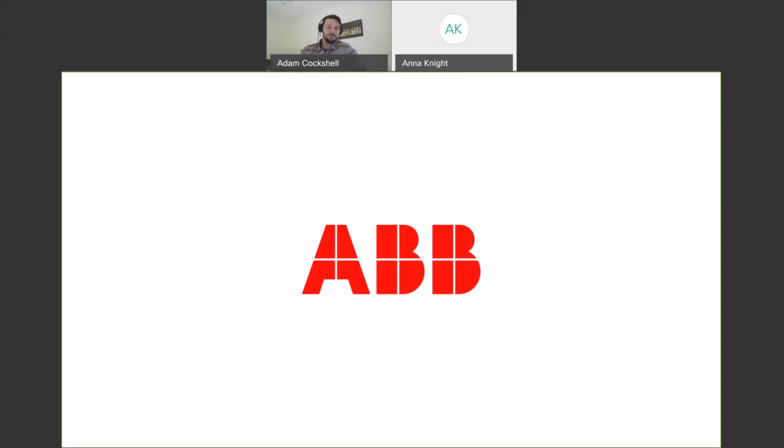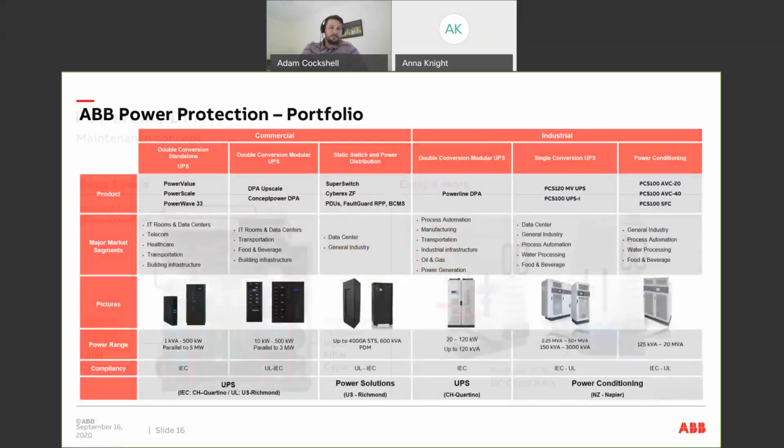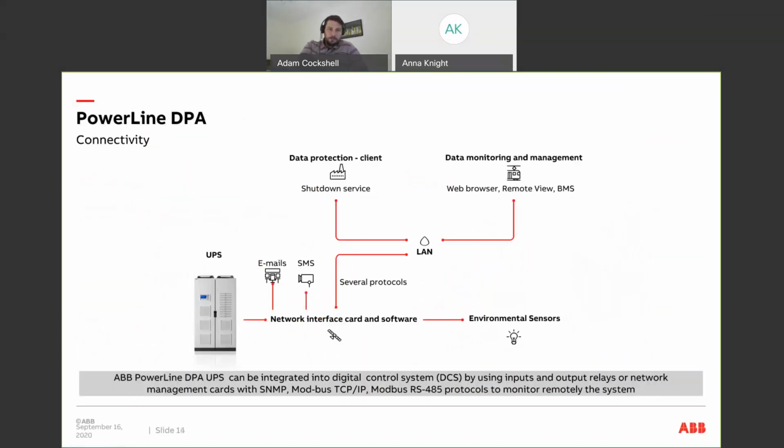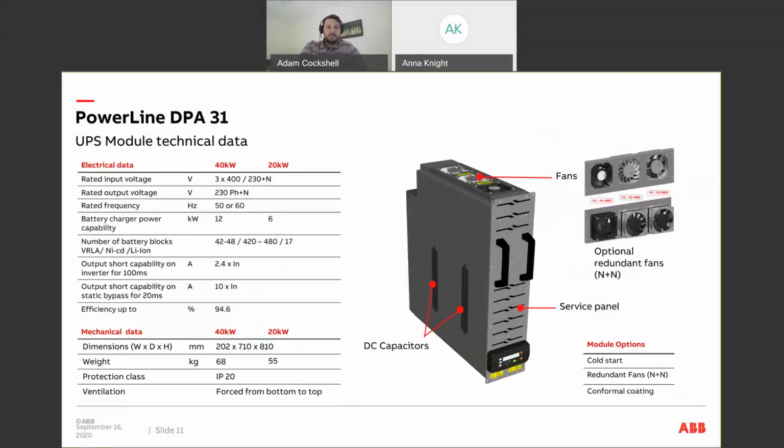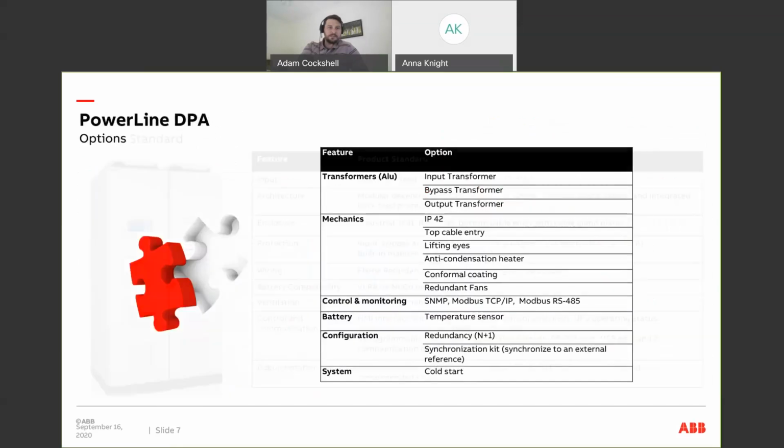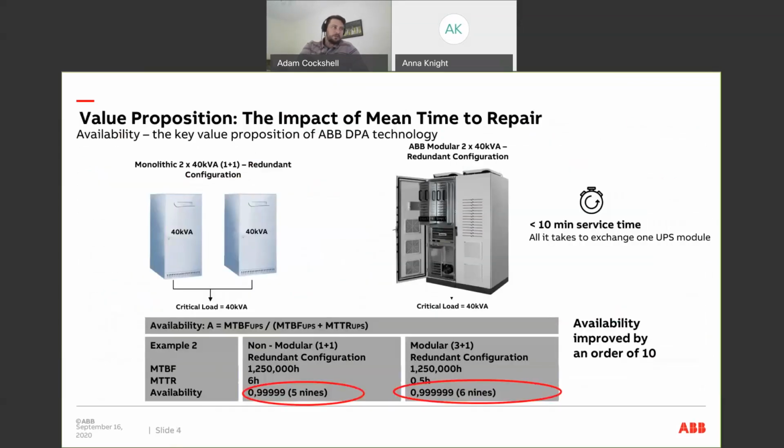Here we go. What is the main purpose of having 2 or more modules with the UPS instead of just having one? So as I made mention earlier in the slide, I'll see if I can jump back and find the slide. It's about availability and about redundancy. If we were to look at an existing single monolithic UPS, let's have a 120 kVA UPS feeding your critical load.